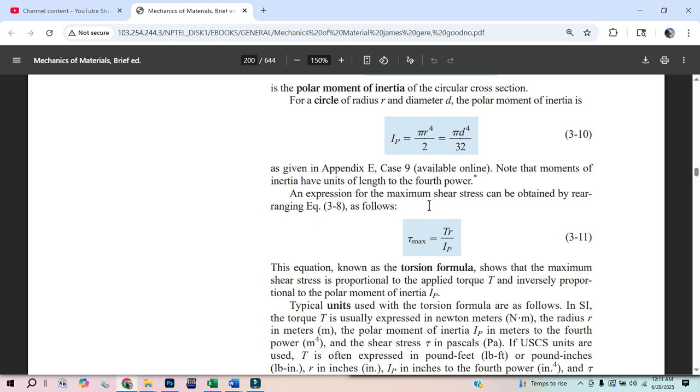Hell yeah. So if we're dealing with steel, I know the max number that I'm wanting, the yield stress, let's say. So I'm using steel. That's all I'm saying. I'm going to manufacture something. I'm using steel. I want to make a solid circular shaft, and I want to apply a torque on it of 100 pound-feet, sorry. And then the question is, what size do I need to make it? So then this equation you can rearrange for r.